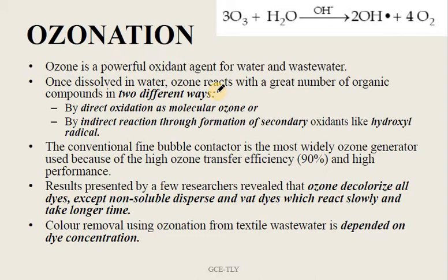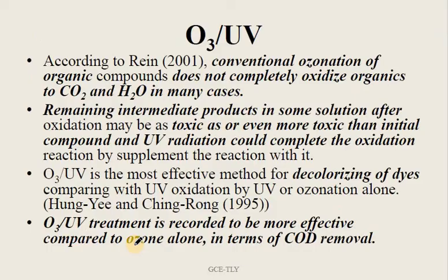So the conventional fine bubble contactor is most widely used because of the high ozone transfer efficiency of about 90% and due to its high performance. The results presented by a few researchers reveal that ozone decolorizes all dyes except non-soluble disperse and vat dyes, which react slowly and take longer time. The color removal using ozonation from textile wastewater is dependent on dye concentration. So dye concentration is an important factor when we apply ozonation for color removal.